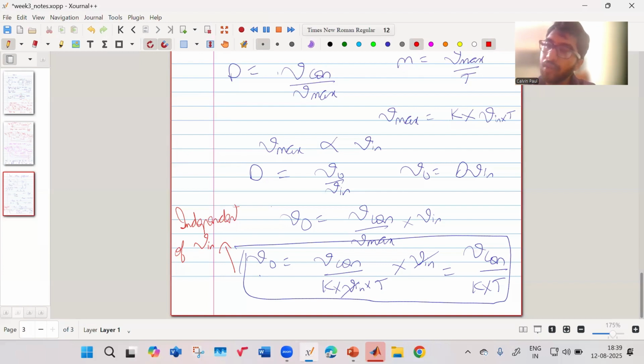So through feed forward control, you can minimize the effect of that disturbance. But these things which I've said are very idealistic. They are not completely true. My assumption is D equal to Vout by Vin, but this is not true, because when the load changes, the drop will change, and the output voltage will not be fixed. It is dependent on the load current, right? This is a very idealistic expression.